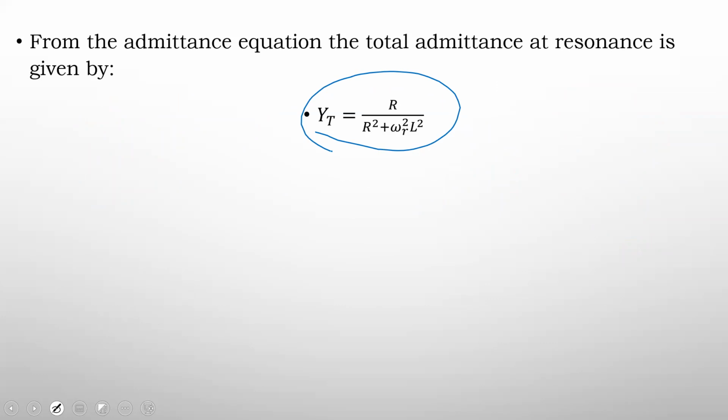Based on the fact that we have no reactive portion, it means that the net reactive power at resonance would be 0. Let me be careful with how I say that. You will indeed have reactive power, it's just that the resultant, the net reactive power, would be 0. So the power dissipated in your circuit at resonance is purely active, as we saw with the series circuit.